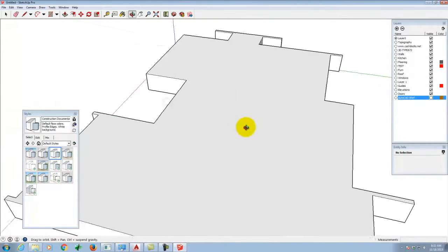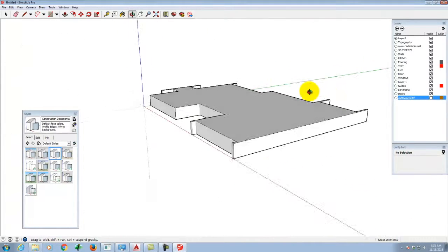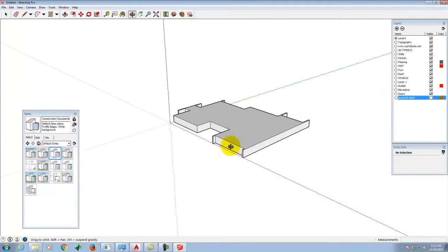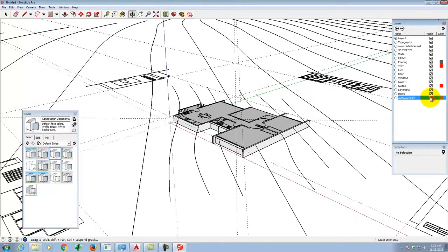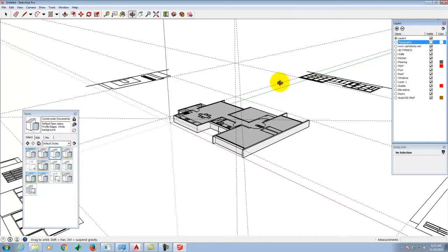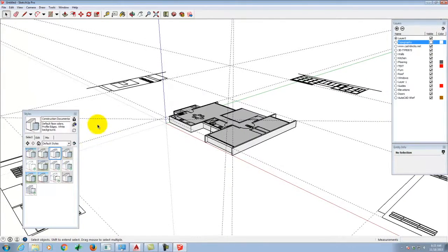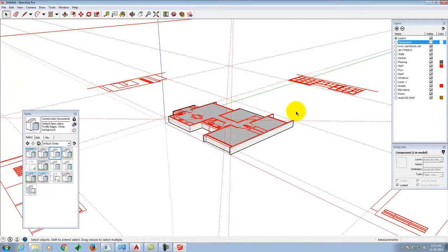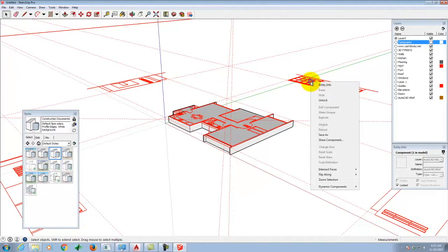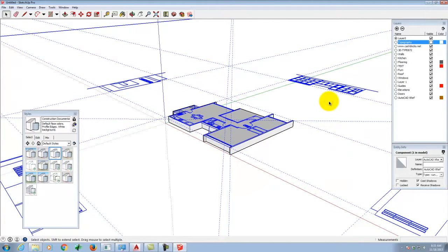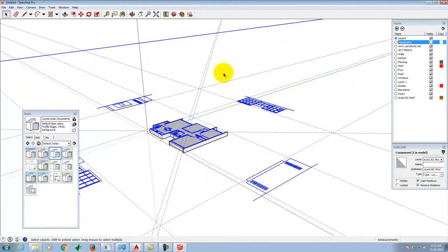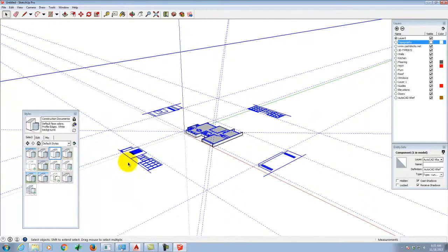Okay? Relatively easy. Now I knew that that 3 feet exists, but I want to spend a little bit more time with the AutoCAD file and specifically the elevations. So let me go ahead and turn off the topography. So we'll uncheck that. And what I'm going to do now is what's called an edit of the component. So again, if I select it, the component turns red because it's locked. I have to unlock it before I can work with it. So let me go ahead and click on Unlock. And then we'll start with this elevation right here.